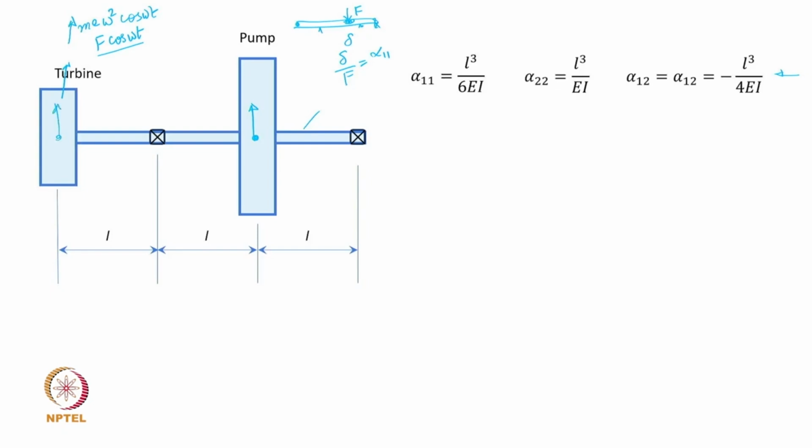Those things aside, if we simplify the problem here to understand how the response to any unbalance or any harmonic excitation to such a lateral vibration system is obtained, what we now say is that y1 is not going to be only given by this, but we include the contribution from the unbalanced force.